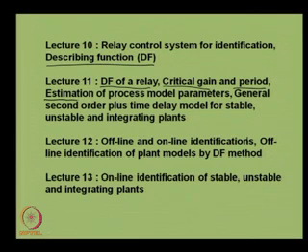And we shall also try to estimate process model parameters, assuming a certain form of the process dynamics. A process dynamics can be assumed in the form of either a first order plus delay transfer function form given as k e to the power minus theta s upon T1 s plus 1, where theta represents the time delay of a process model, k is the steady state gain, T1 is the time constant of the